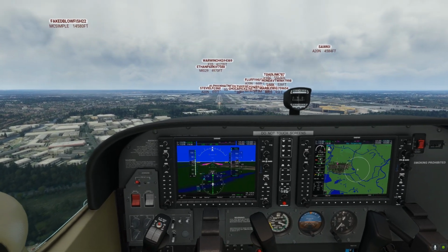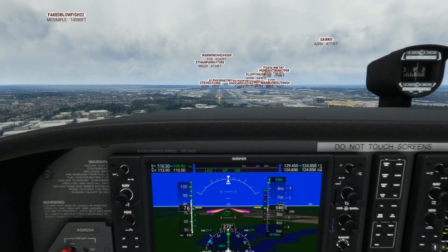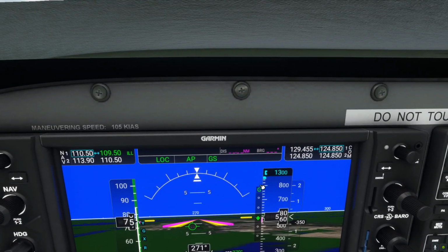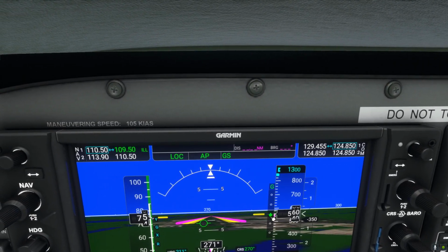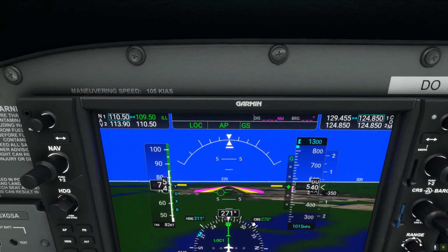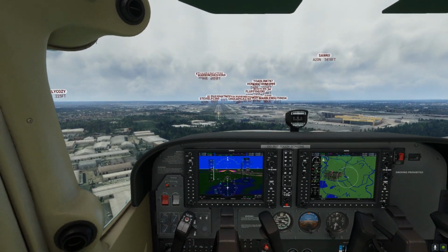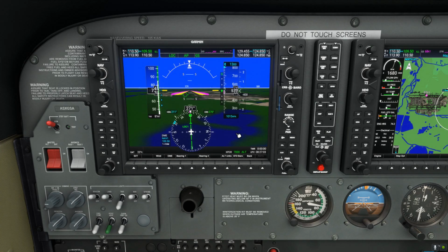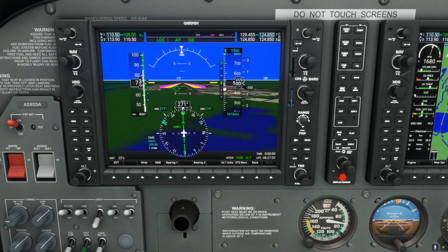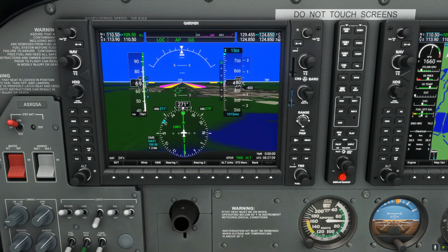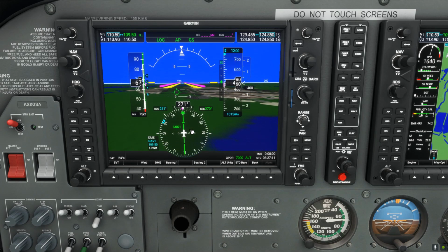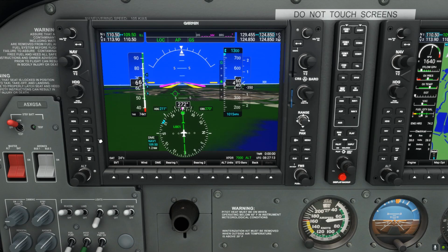All very straightforward. So that approach mode, when it's too late, if you see the glide slope indicator move down and you've not pressed approach mode, so you're all lined up. Sorry, let me just take the Tobii eye tracker off for a second so I can concentrate on this screen without moving around. This glide slope indicator starts moving down and it goes below, so it's down here somewhere. You're all lined up, but you've missed it, and you press approach mode.